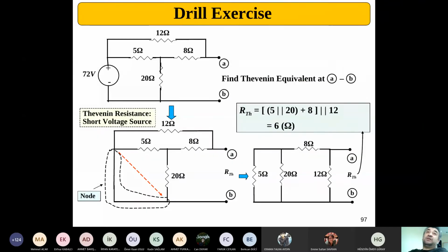Now let's try to go and find the corresponding Thevenin or Norton equivalent circuitries for this example. As you can see, using source transformation here will not be a good one. But since we have only one dependent voltage source in here, maybe finding the equivalent Thevenin resistance is kind of easy. Just short circuit these two terminals and looking from this side on, see how the resistors are connected.